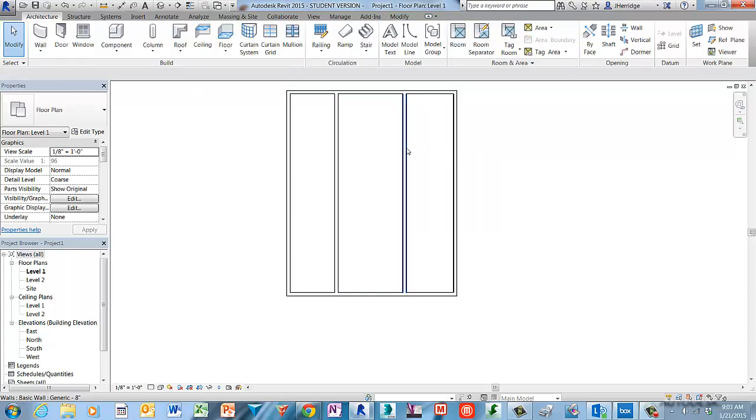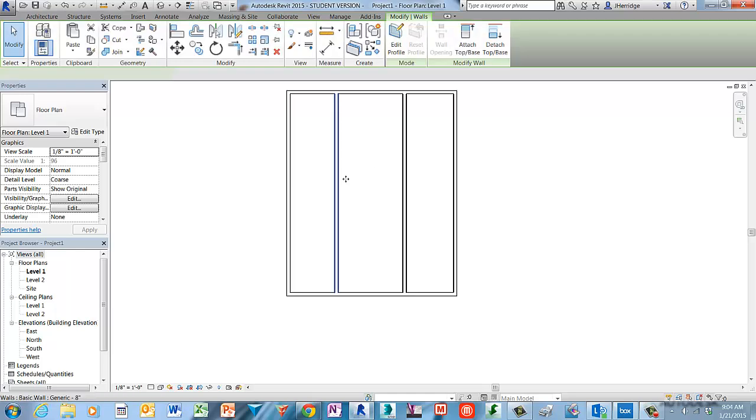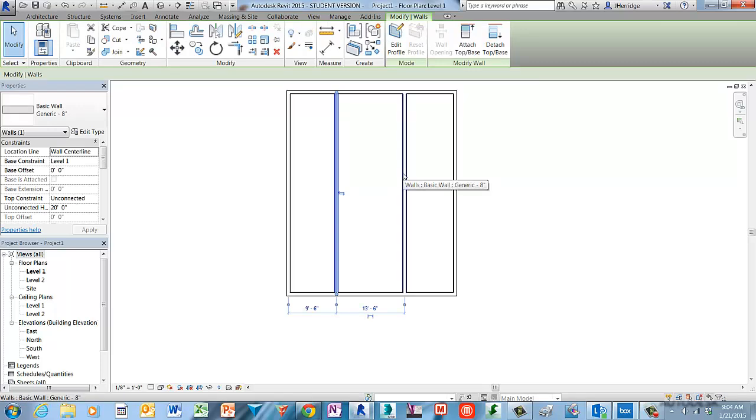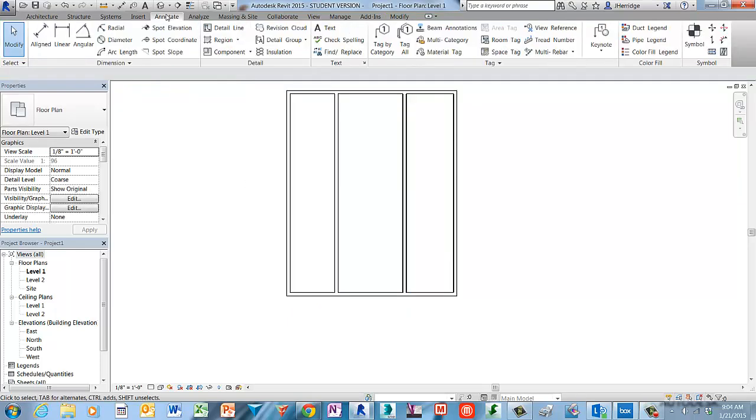Using your existing CAD knowledge, you could measure the distances between the walls and then figure out what the movement dimensions need to be. But there is a better way with building information modeling. We can simply create a continuous dimension string across the walls that we wish to establish a relationship with, and then enable what's called an EQ constraint to actually create a parametric relationship. So again, these are the 2 internal walls that I want to become equal to create those 3 spaces.